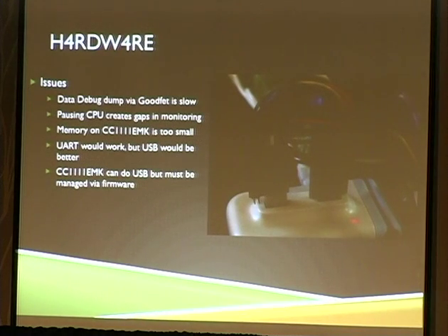So the issues that we have in this environment is basically, it's a development environment, so debugging data through the GoodFET is slow. What it does is it stops the CPU, pulls the data off, and then restarts it. So I'm missing that big swath of time, and we can probably get that down to a second, but that's huge when we're talking about frequency hopping. That's a drawback. Also, obviously, the memory: I have to scrape memory at a certain point, or else it's just going to overflow, or I'm going to overwrite my old data.